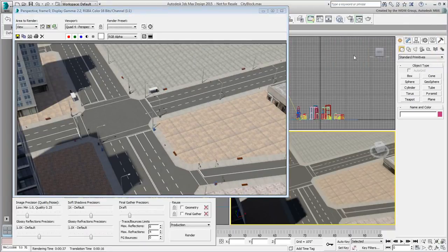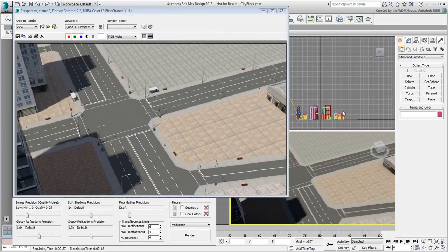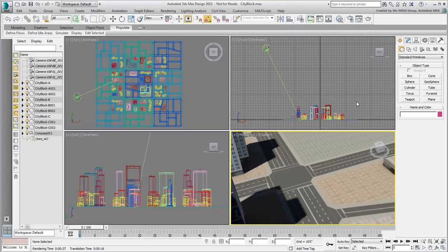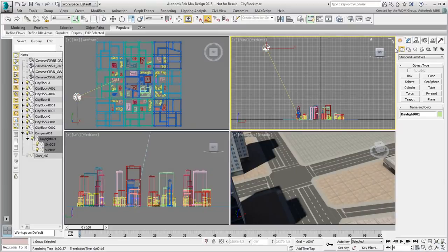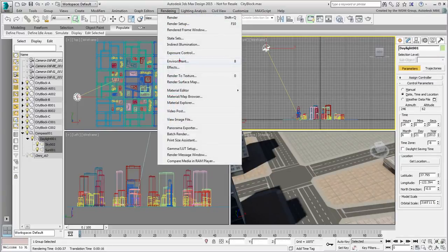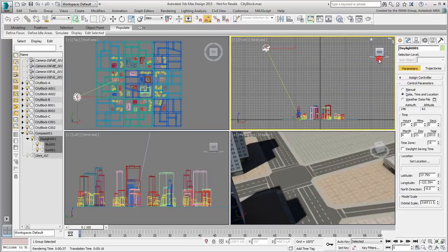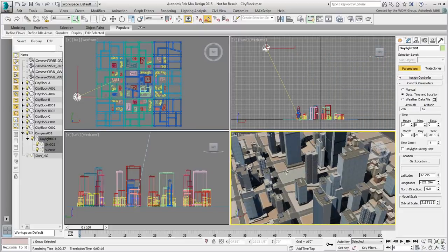That's courtesy of an option named Render Hidden Geometry that you can enable in the Render Setup dialog. More importantly, you'll also notice that the scene already contains a daylight system set for an early afternoon render. Other adjustments, such as exposure control and a background, have already been set. Because the daylight scenario is already in place, you wouldn't want to add another daylight system coming from Revit.